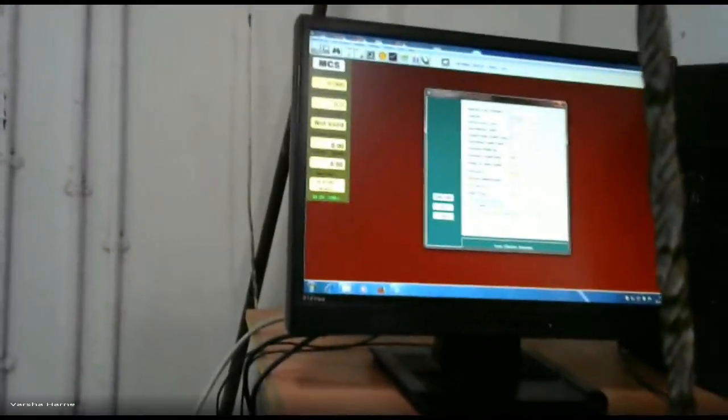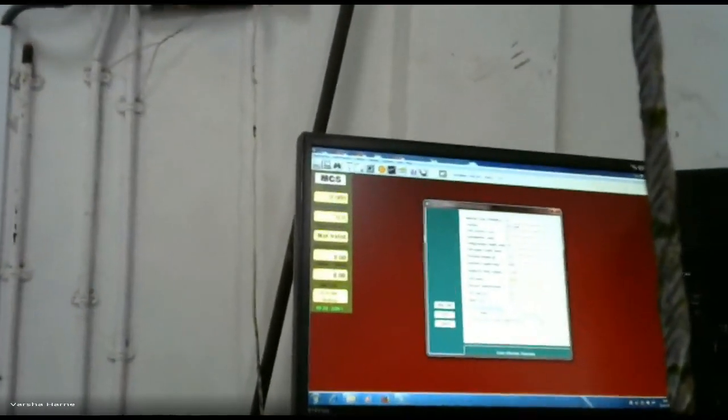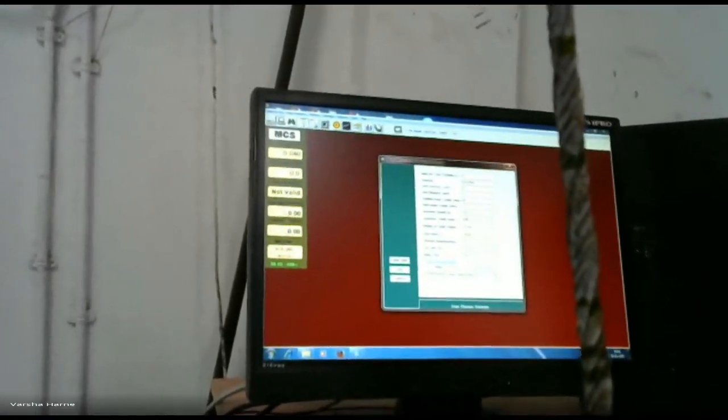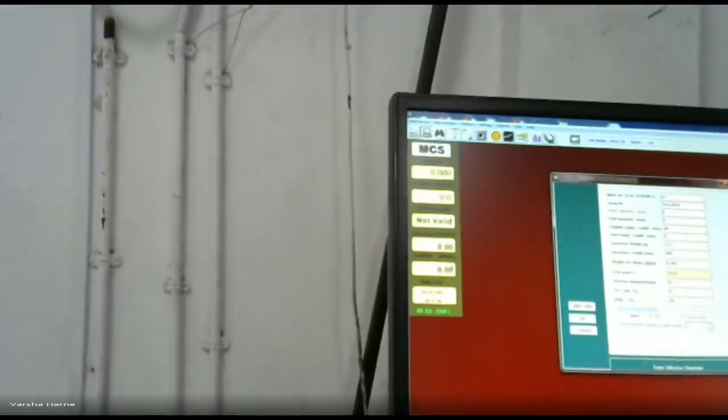If you see the weight per meter, it is automatically calculated. If I put the diameter, it can automatically calculate the effective area. Now here there are two parameters, called preload and delta. That preload totally depends on our loading rate. If you see the loading rate here, it is in kilonewton per meter.